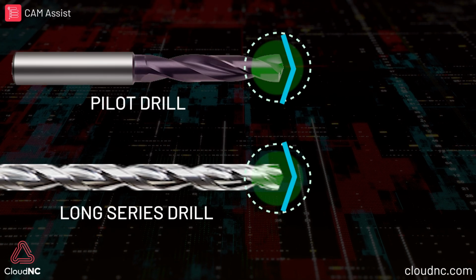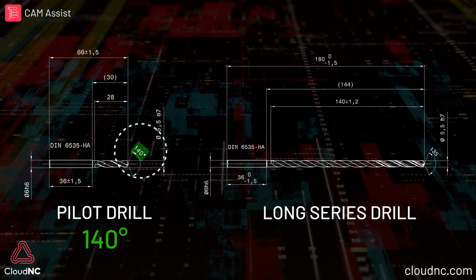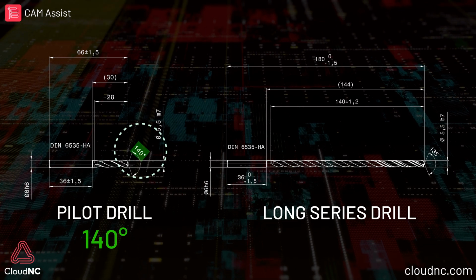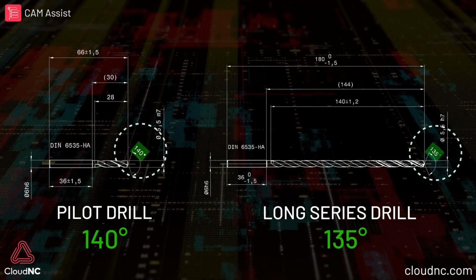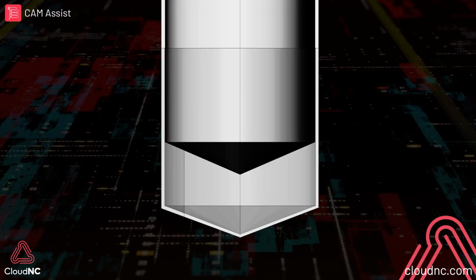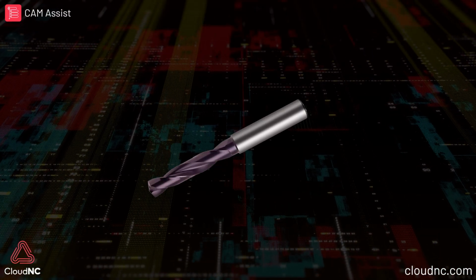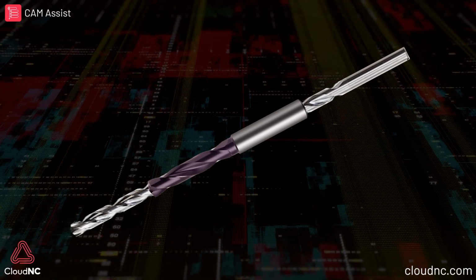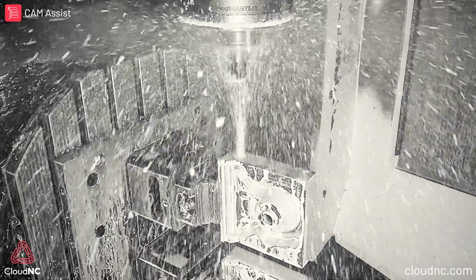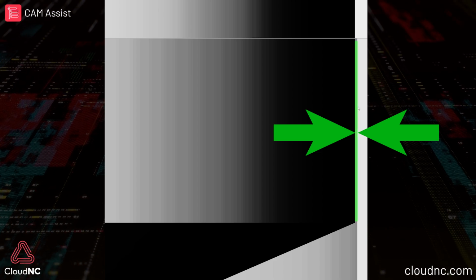Ideally, the pilot drill should have a larger point angle than the long series drill. In this example, the pilot drill has a tip angle of 140 degrees, whilst the long series drill has a tip angle of 135 degrees. This ensures that the tip of the long series drill meets point to point with the tip of the pilot drill. The pilot drill should have a larger diameter than the long series drill by a very minimal amount. This is to allow a small amount of clearance between the cutting edges of the long series drill and the pilot hole it feeds into.